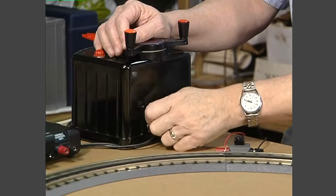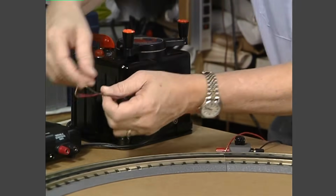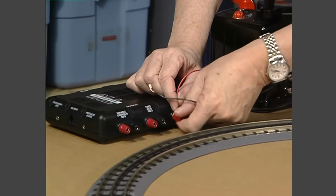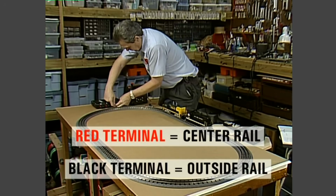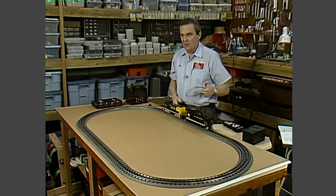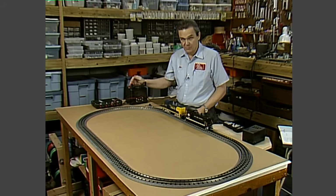I'm going to remove the wires from the transformer and connect them to output channel 1 on the TIU like this. The red terminal should be connected to the center rail and the black terminal is connected to the outside rail. I've got another set of wires that I'll connect between the transformer and the input channel 1 on the TIU.